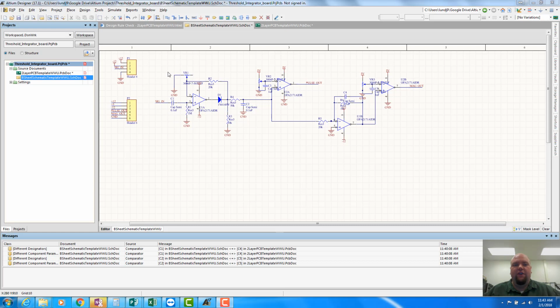So what we're doing here is we're taking that preamplified signal, and taking it through one more round of amplification. In this additional round of amplification, we have a pot here so we can adjust the gain to get the levels we need. We also have this op-amp circuit here. You'll see it has a diode at the output. That's a good way to halfway rectify the signal.